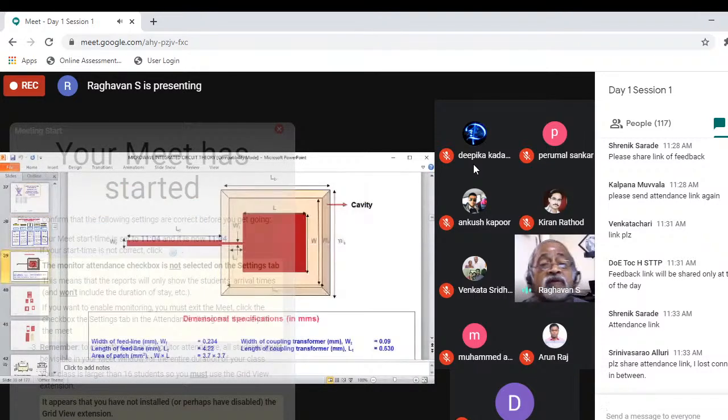Now, you take a simple patch antenna. Normally people say use already available expressions, but one can easily get those expressions. This patch antenna has one length and a width. The length is almost lambda g by 2, a resonator. You just subtract the effective length, the correction factor delta L, on the left side and right side. That is how the length and width values are a little different.